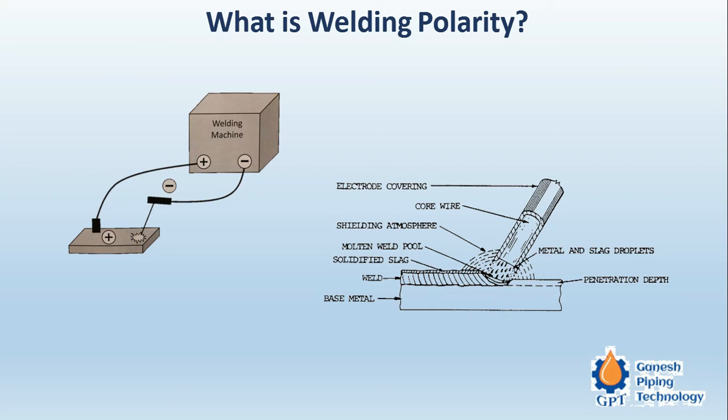For example, if we have welded two plates, and because of some reason we have to separate these two plates by removing that welded joint, we can use gas cutting, but in case of stainless steel we cannot go for gas cutting. So in that case we can use gouging. Of course, for carbon steel plates also we can use gouging if we don't have the gas cutting facility.